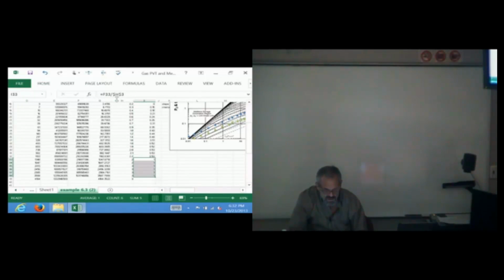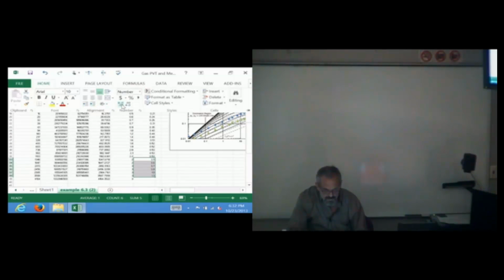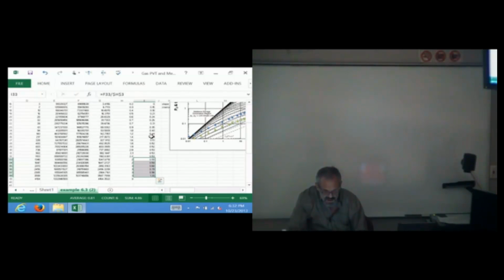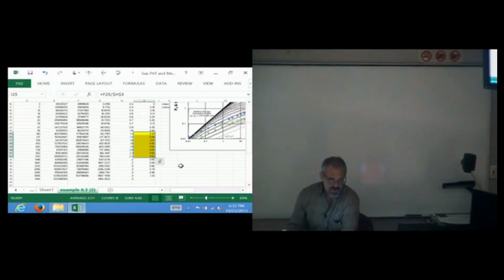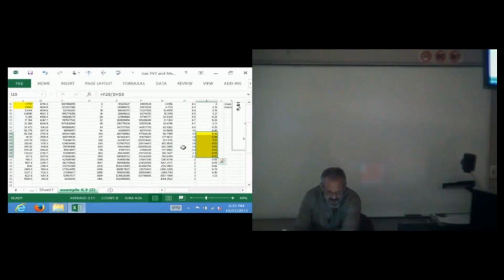Let's get a couple more in here. So that's telling me in this 0.44 range to this 0.53 range, that's where I have radial flow. After I've matched it on there, I'm going to have radial flow there. So I can probably come all the way back here because I'm eventually going to have to grab a time series. And I think this is my time series here. I'm going to highlight those two. So there's my radial flow regime.